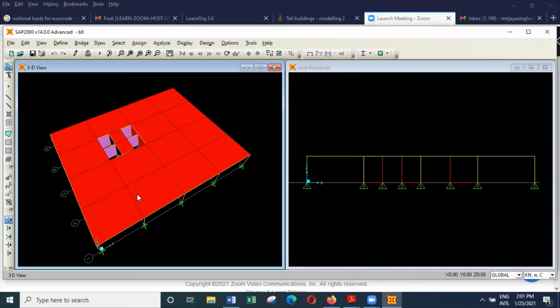Before generating the other floors, we have to see whether we are going to use the same column size throughout the height of the building. Here I'm going to consider something like 30 floors for the building. Floor to floor height is 3.6 meters. So we can get an idea about the complete building, and also see what are the important parameters we will have to perform calculations on.